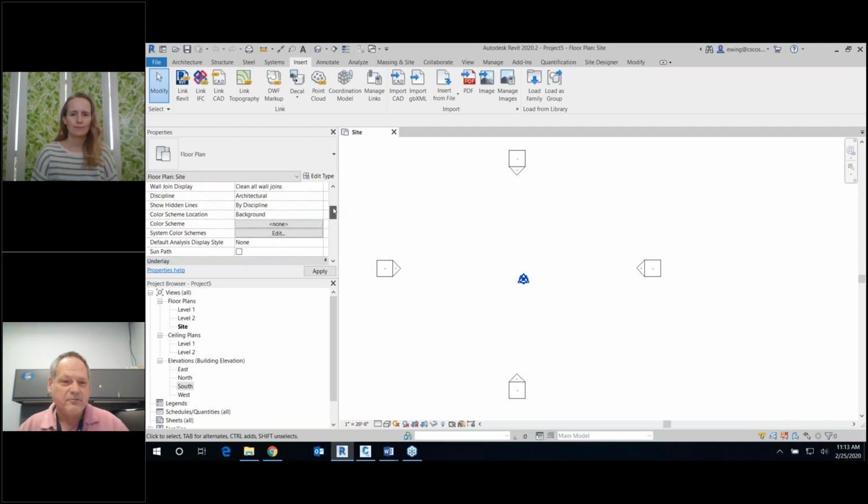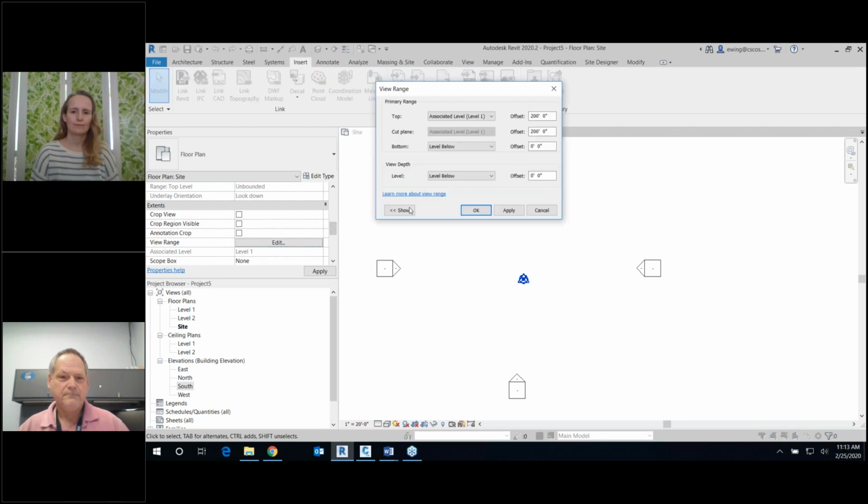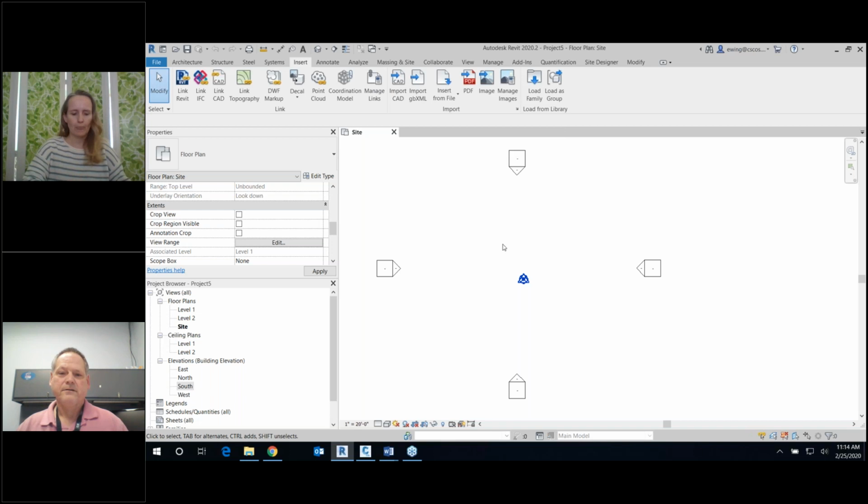So if I scroll down a little bit, I just want to tweak my view range. So I want my top to be unlimited. Let's see, as high as humanly possible. My cut plane, I think I'm around 1,500. I know Michelle's out in Utah. She's used to the higher planes. So my bottom, I'm going to go unlimited. My view depth, I'll also go unlimited, right? Just so I can see everything. And I'm going to hit apply, then okay.